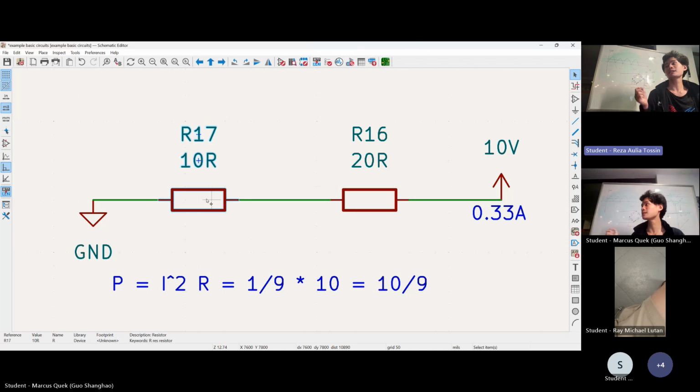When we are designing circuits that care about power, like stuff that's battery operated where you don't want to waste battery, suddenly you have to think about how much power each resistance in your circuit draws. We'll show you in future lessons when you really need resistors and how to choose resistor values such that they get the job done without using too much power. For now, just for your information, you lose power every time you go across a resistor. The resistor will dissipate that power as heat, because that's how resistance works. We take some of the current and turn it to heat.